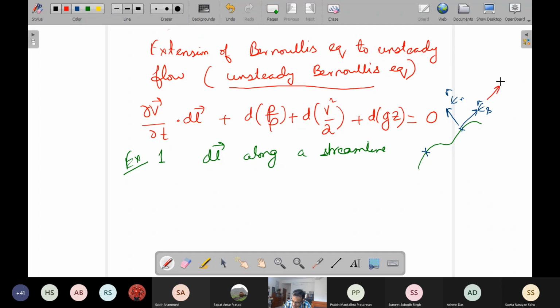That is the definition of the streamline. We cannot really argue about that because it is defined in that way, that the velocity is tangent to the streamline. Therefore, no matter what the velocity field is, locally it is always aligned with the direction of the tangent, and therefore the streamline converts a 3-dimensional problem to a local 1-dimensional problem.